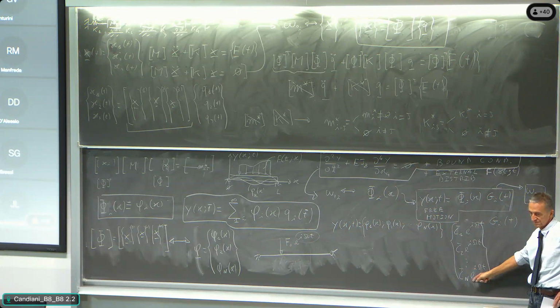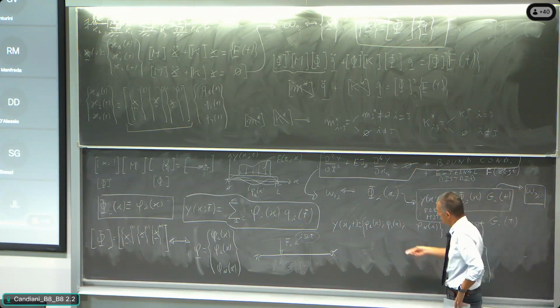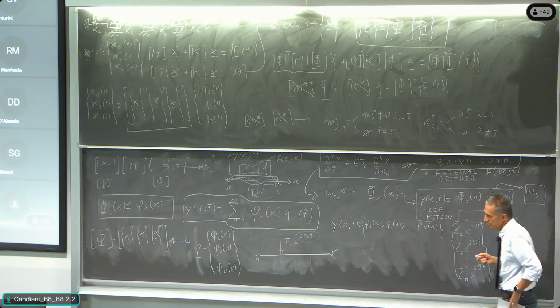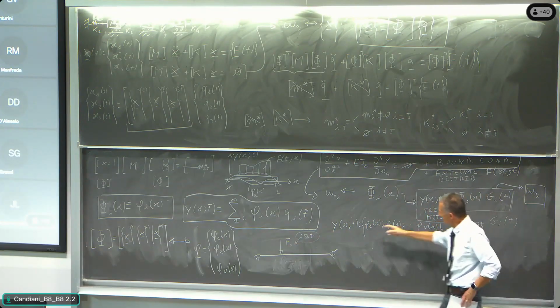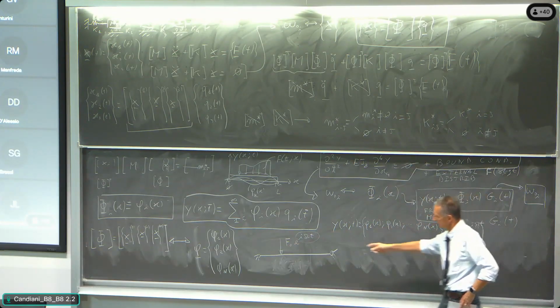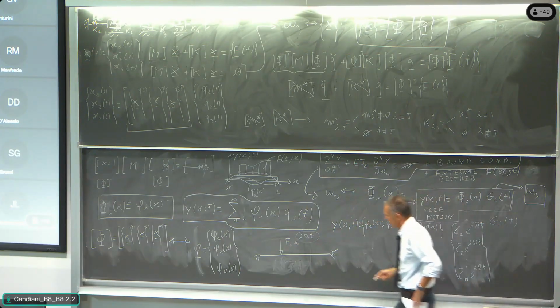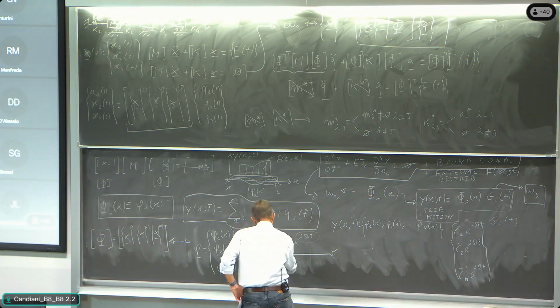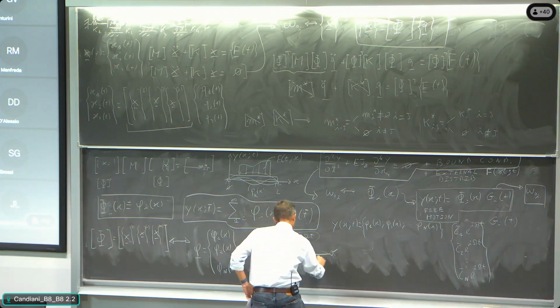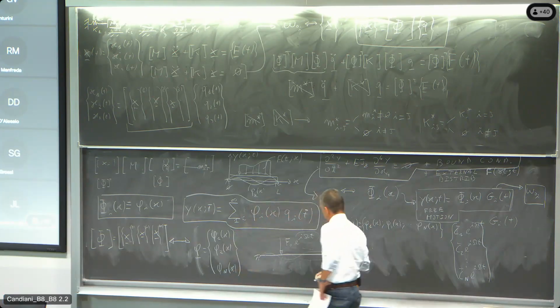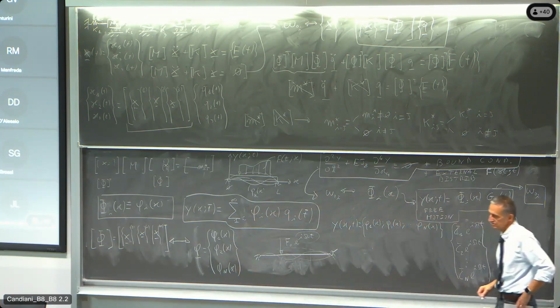A complex constant that is saying which is the amplitude and the phase with which the mode 1 is answering to that excitation, the magnitude and phase with which the mode 2 is answering to that excitation, the magnitude and phase with which the mode 3 and so on are answering to that.